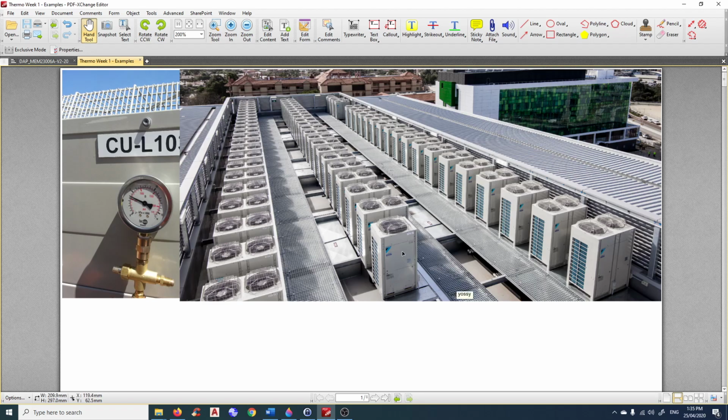To do that, once they finish with the bracing and connecting all the copper pipe back from the condenser to the fan coil unit at the floor below, we pressurize the system with nitrogen, as you can see here. We pressurize it to about 3,800 to 4,000 kilopascal for 48 hours. If after 48 hours the pressure remains the same, then it's all good. The system can go into vacuum, so we hold a couple of 100 micron for 24 hours. If the vacuum holds, it means the system is leak free. Then they can start charging with the refrigerant gas.